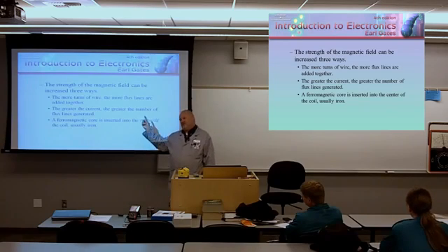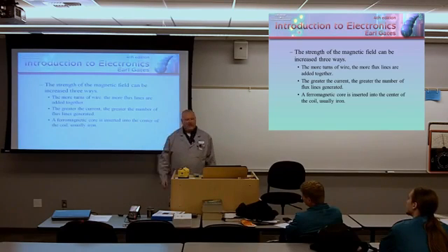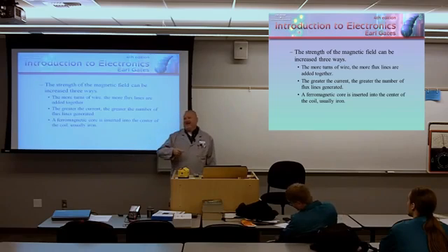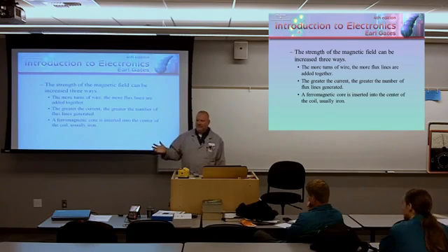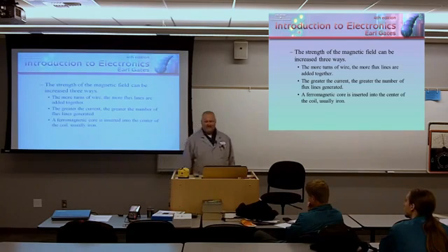So once you have too much current go through that coil, you're going to compromise that lacquer coating, and that's the end of your coil. By the way, if any of you have ever smelt a coil, that's the end of the coil. By the time you smell it, it's over with. You've already compromised the integrity of it. It'll never work right again. Transformers, motors, coils, any of that stuff. If you smell it, if it gets that hot, forget it.